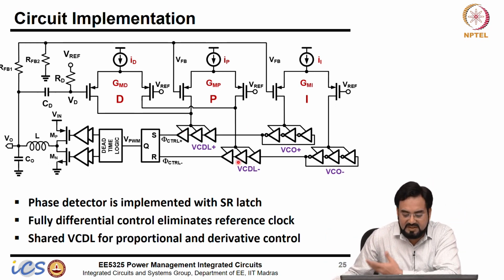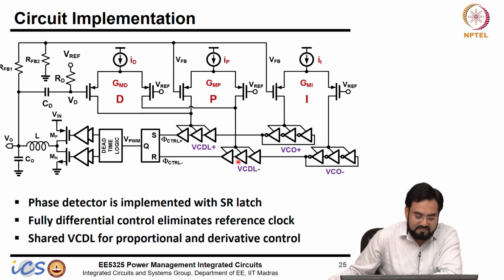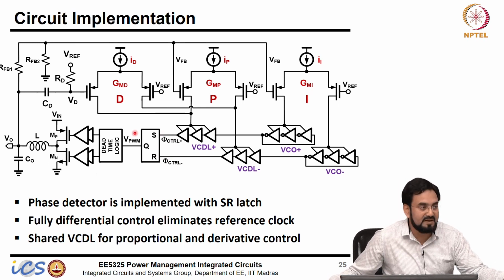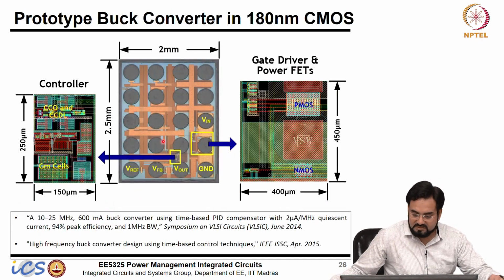And that was the main reason we can push it at much higher frequency. So, at one edge we reset, set, other edge we reset, that is it. So, this SR flip flop will simply behave like a phase detector. So, this was the chip we implemented.